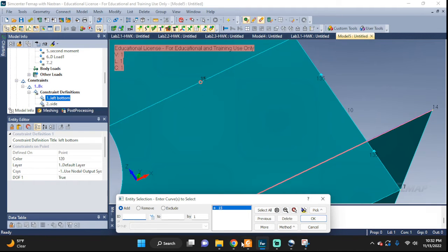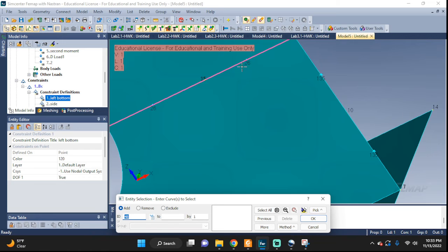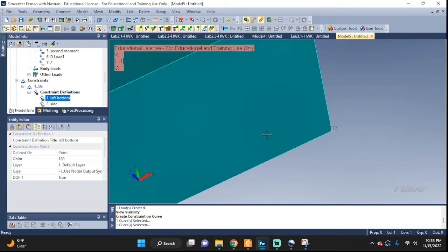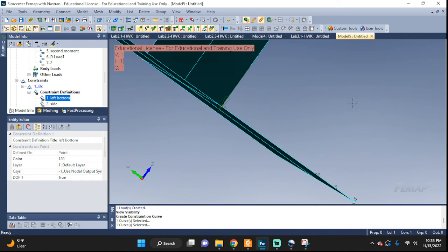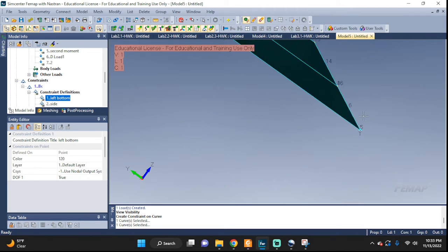If you don't know what 1, 2, 3, 5 mean, well, let's go back. Let's try to apply another, just so we can bring the dialog box back up. So see, 1, 3, and 5, these are numbers that represent these 6 options: 1, 2, 3, 4, 5, and 6. So if I would pick, I don't know, 2 and 6, then that's what it's going to display right here, 2 and 6, right? So that's what the numbers mean. When it put a T for us, that just means that the translation is restricted. Instead of putting 1, 2, 3, some older versions of the software used to do that, but now they just put a T.